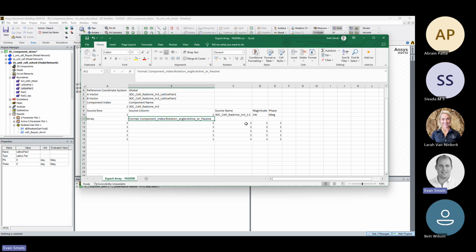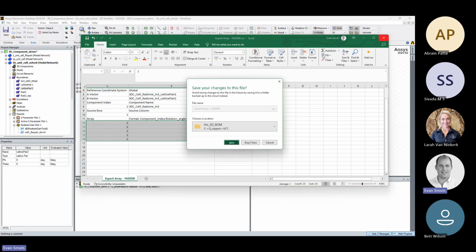And in this case here, this is where we start actually looking at the sources. Okay, so the source is up here because we just have a single source. So in this case, we're just powering it with 1 watt and 0 degrees. But then in the array, we can then alter all of these. For example, if we do some beam steering, we'll see it will look a lot different.